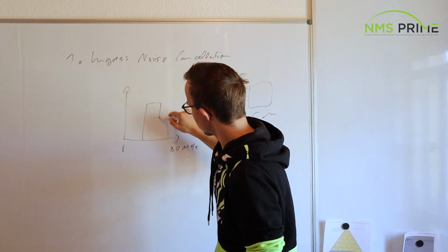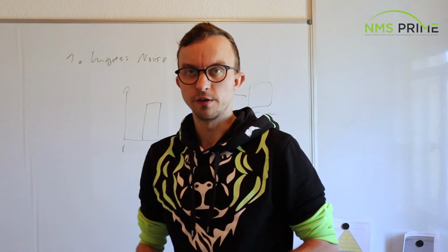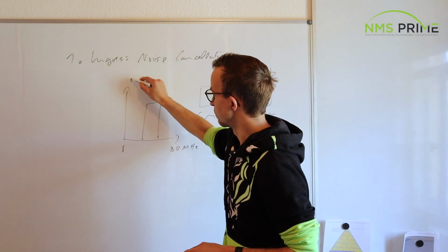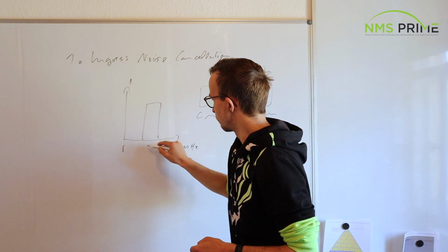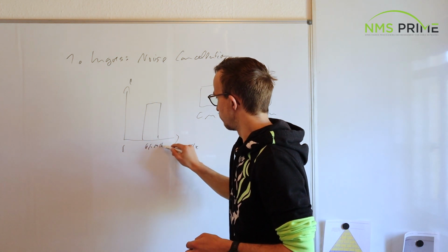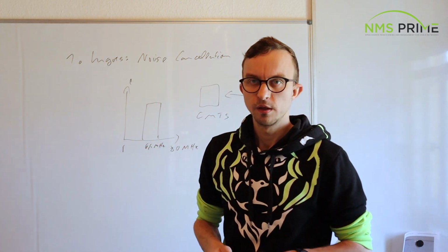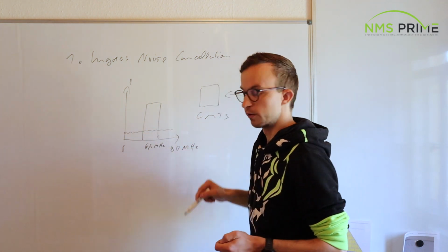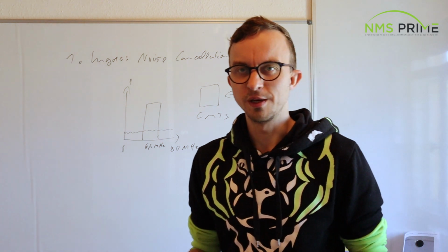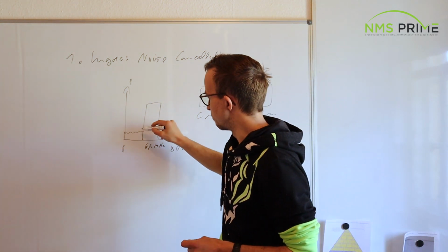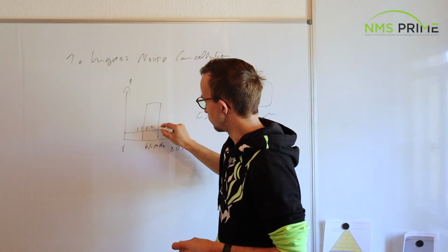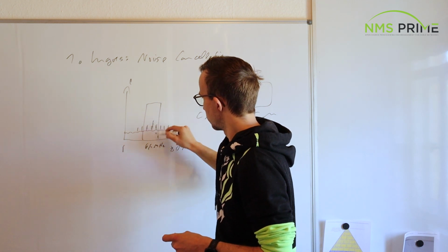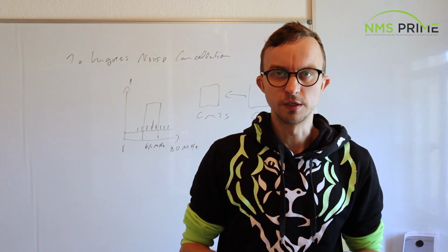And this makes maybe some kind of rectangle function inside the frequency spectrum. And here we have maybe 6.4 megahertz of bandwidth, and of course we have a noise floor inside our cable plant, and then we have some impairments, maybe just some interferences or something like this, maybe some stronger ones. And what is ingress noise cancellation?